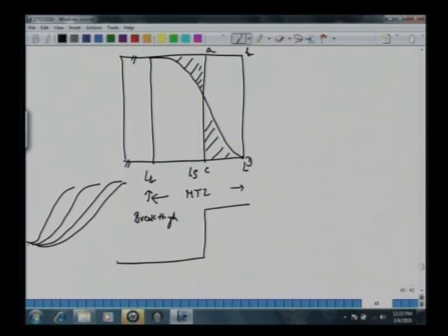Another way of explaining that: if everything is ideal, or there is no dispersion, or all kinetics are fast, all rates are fast, pore diffusion, mass transfer coefficient, interface mass transfer, and everything is decided by the rate of adsorption and desorption, one would expect the front to go like this. What we experience in a practical sense is a curve like this, which is non-ideal. Had this been ideal, the response of this breakthrough curve would have been like this. So there is a non-ideality.